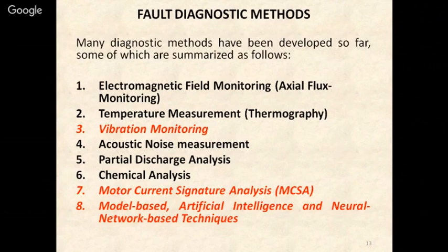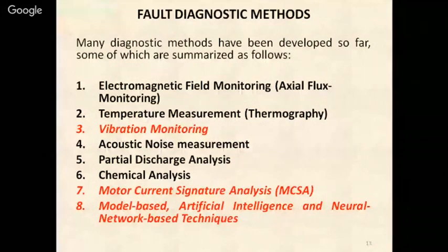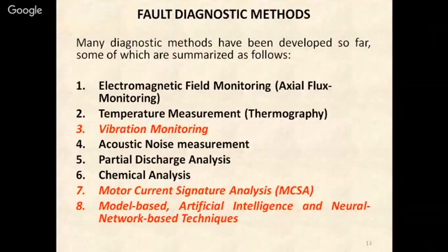Whenever a motor is failing at a particular time instant, it will cause some change in the characteristic signals: vibration may increase, the motor may heat up very early, and it may cause a very peculiar acoustic noise in the environment. All these signs can be measured and fed to a diagnosis system so that we can have early detection of motor failure.